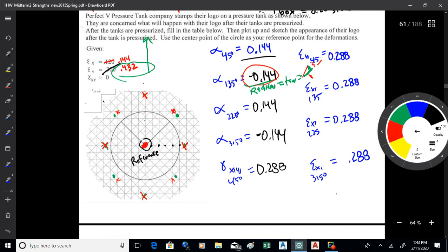And if I were doing this for real, I'd probably calculate these. I'd probably create a spreadsheet that just ran the numbers for me. I'd plug in every 10 degrees. I'd plot those points up, and then I'd connect them with a spline and run it that way. I mean, that might be a reasonable way to do it, okay? And you'll get the final shape. So after this tank is pressurized, and I'm not doing a very good job drawing here, this is probably what it ought to look like.